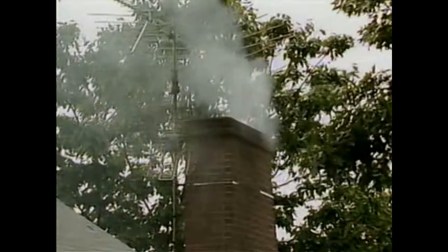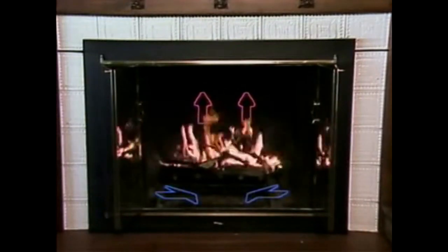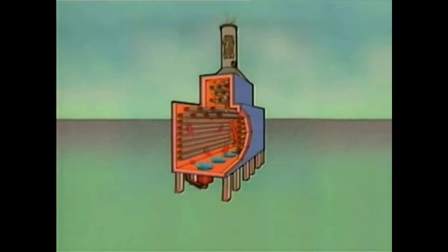This reduces the pressure inside the fireplace. As the hot air rises, it's replaced by cooler, heavier air in the fireplace, and the process continues. In a natural draft furnace, the hot combustion gases, which are lighter than the outside air, rise up the stack and create a lower pressure in the furnace. As this occurs, cooler, heavier air from outside the furnace is drawn into the burners through the air registers.